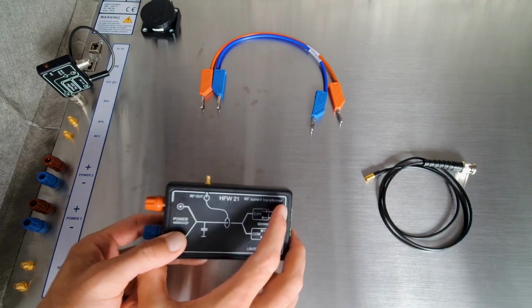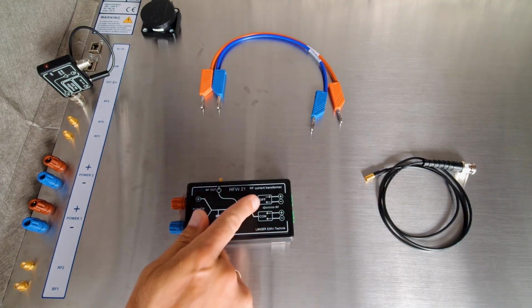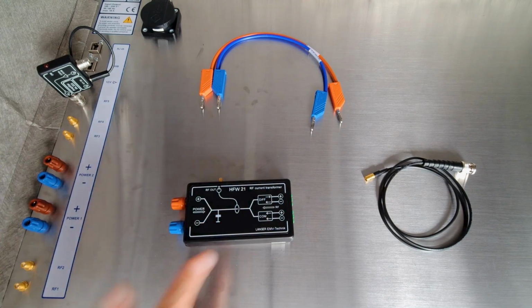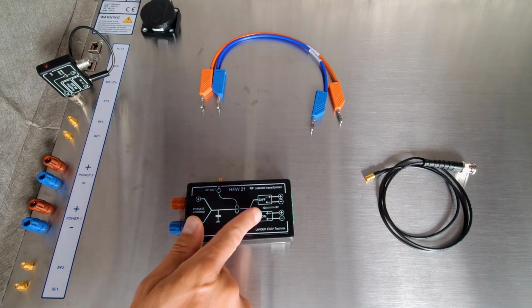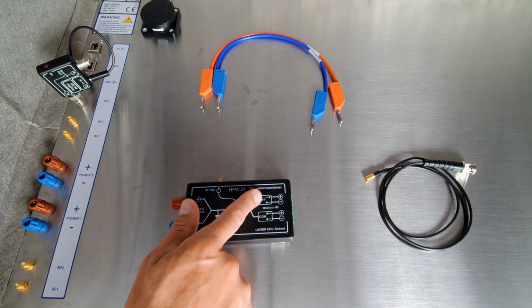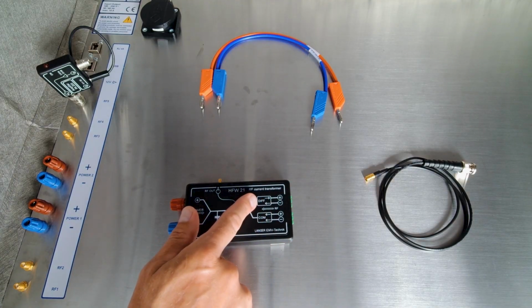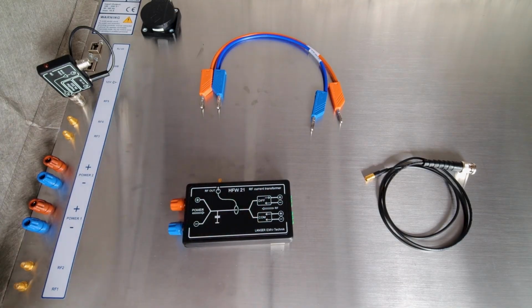signal is put out. So then you also have, for conducted measurements, two possibilities here. One possibility is to measure the common mode disturbance current, and on the other side, the second connector is to measure differential currents. Later I will explain why it is sometimes important to measure common mode or differential mode.